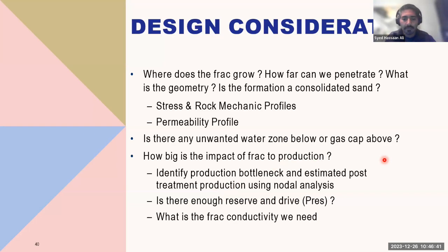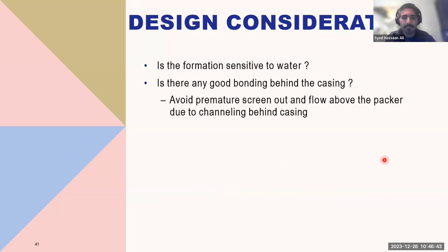You want to make sure that your payback time period, your return on investment, makes sense. And then also how sensitive the formation is to water, and is there a good bonding behind the casing. Behind the casing, we have cement, and we want to make sure that there is a good bonding there, because if there is not, there will be a secondary flow path above the packer due to channeling behind the casing. So you will have flow behind your casing, which you don't want.